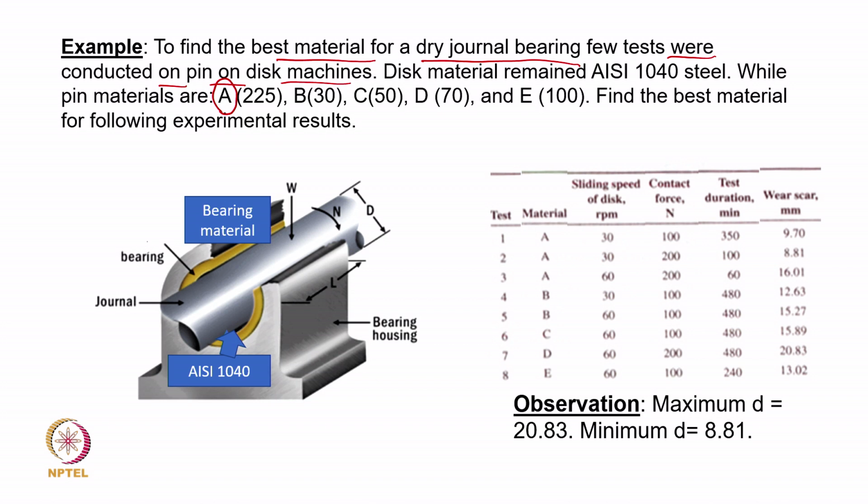Again, the Archard equation gives a qualitative nature, not a quantitative nature, and we need to perform experiments. The Archard equation indicates which parameter needs to be considered and optimized using the experimental technique. We can go ahead with a much more detailed analysis, but for quick results we can get direct results from the pin on disc machine in this situation.